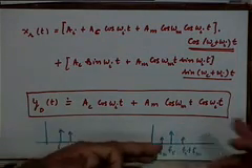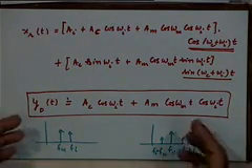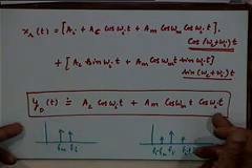So in a way, the presence of a large interfering signal degrades the output to the extent that it is as if the modulating signal is not coming out, but is modulating the interfering tone, omega sub I. So I hope you understand that the envelope detector works very nicely as long as the interference is small, but if in some situations the interference becomes large, this doesn't work well. That will be our conclusion for today. Thank you very much.